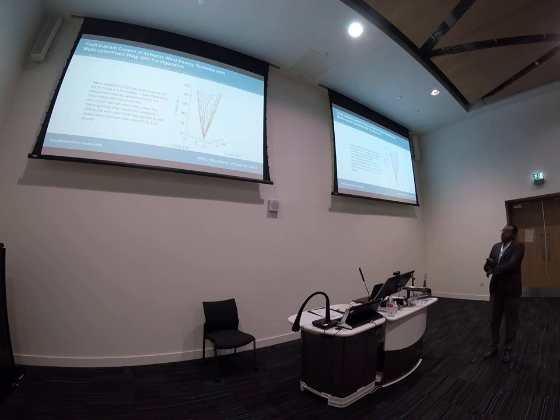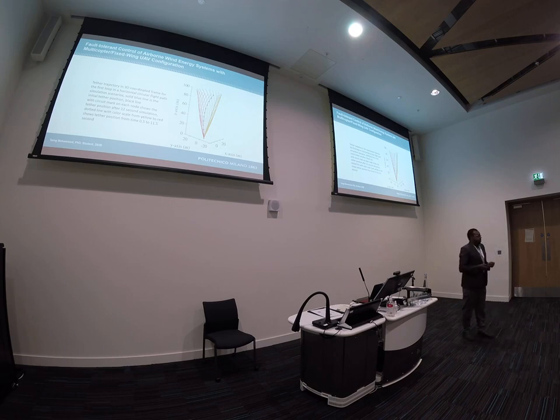It is not only about modeling the aerodynamic characteristics of the kite, it is also about building a good tether model. This is the tether model, which considers the aerodynamic effect and the mass, and we also validated it through some simulation.